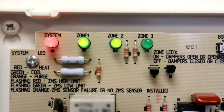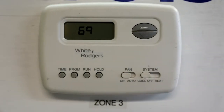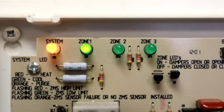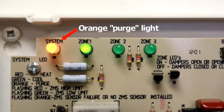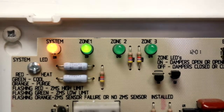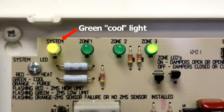So what if Zones 1 and 2 are already calling for heat and then Zone 3 calls for cool? Zones 1 and 2 must first satisfy their calls for heat. Then the system will purge for roughly 3 minutes by running the blower to remove any heated air from the ducts. At the end of the purge cycle, the zone control panel will close Zones 1 and 2, open Zone 3, and turn on the AC system to supply cool air to Zone 3. Anytime the system switches from heat to cool or cool to heat, it goes through this purge cycle.